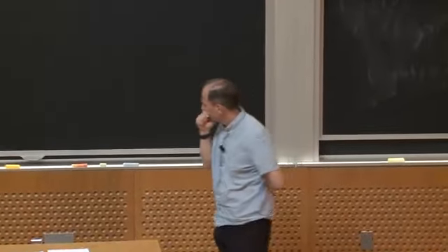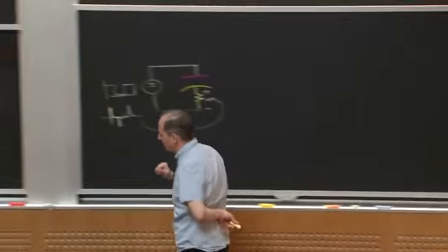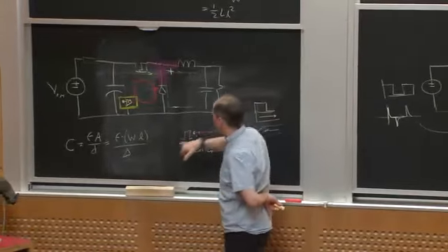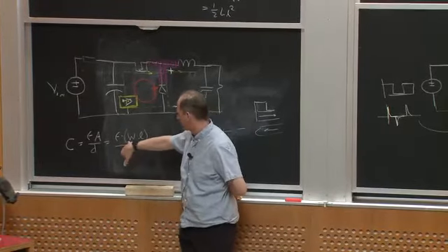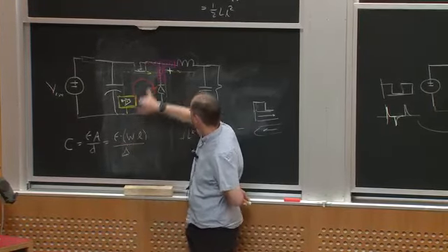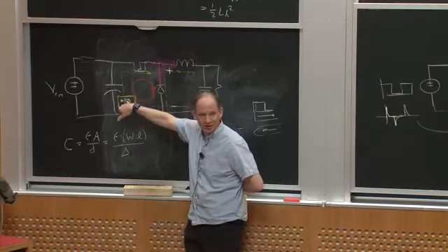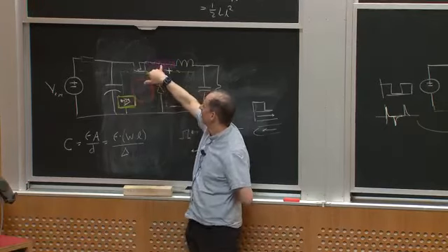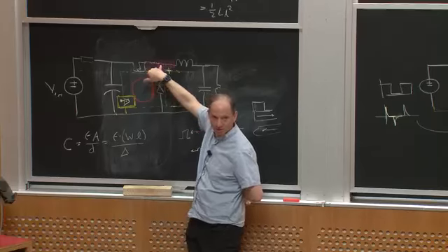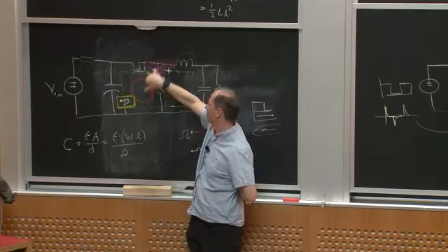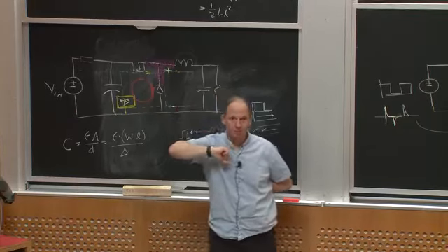So what can I do about that? Well, one thing is, the capacitance is related to the area. I assumed the two plate areas were the same. Here, this is some small area that's this node. This is some big area that's associated with carrying currents for my switching node. One thing I want to do is make that as small as possible.